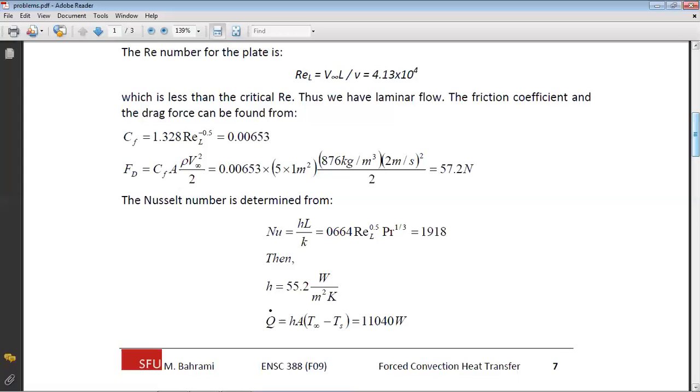And using that, if you substitute the value, the Nusselt number is equal to 0. So here is a mistake. There should be a point here. It is 0.664 Re to the power 1 by 2 into Prandtl number to the power 1 by 3. We have calculated the Reynolds number. We have noted down the value of Prandtl number from the data handbook. If you substitute, you will get a Nusselt number of 1980. So this is the average Nusselt number.